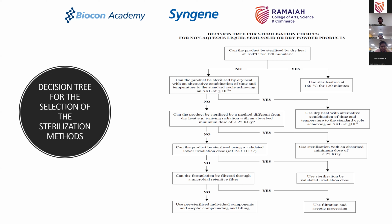It's called a scalper or a refiner kind of equipment. It is a variant of a filtration device where you could load a slurry into it, filter it, wash the powder, and do whatever you wanted with the powder in terms of treating it or washing it out to remove all residual solvents, and then dry it within that equipment, all under sterile conditions, and then unload it in a sterile closed condition, and directly take it for filling on a filling machine. So that's one example of the equipment.